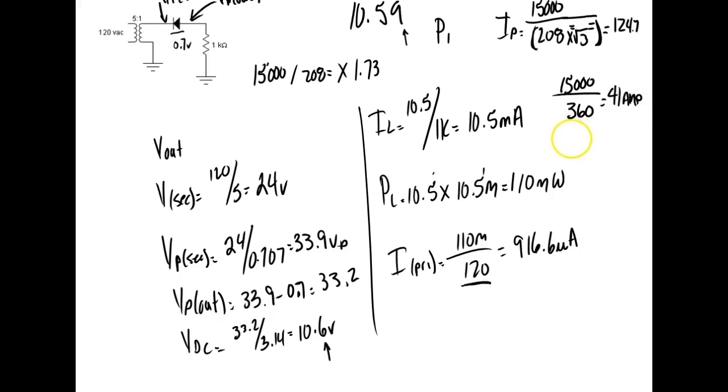The secondary current: this is a step-up transformer, so it's a 208 to 416 transformer. So my secondary current would be equal to 15,000 divided by twice that, which would be 416, right? Times the square root of 3. So it's a 1 to 2 transformer. So that's going to be 15,000 divided by open parentheses 416 times 1.73 close parentheses, equal to 20.8 amps, about 21 amps.